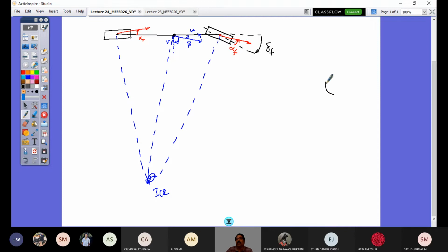So you can also see that if I have a wheel, right? So the wheel is hinged here. Bicycle is on a stand and wheel is rotating, rear wheel. Then it will be only rotation. If the bicycle is ridden, you look at the same wheel, it is undergoing what is that motion called, a general plane motion. That means the CG will translate as well as it is rotating. So if that is so, what is this velocity you get? If the surface is rough, it is not sliding. So this point is what is called an ICR.